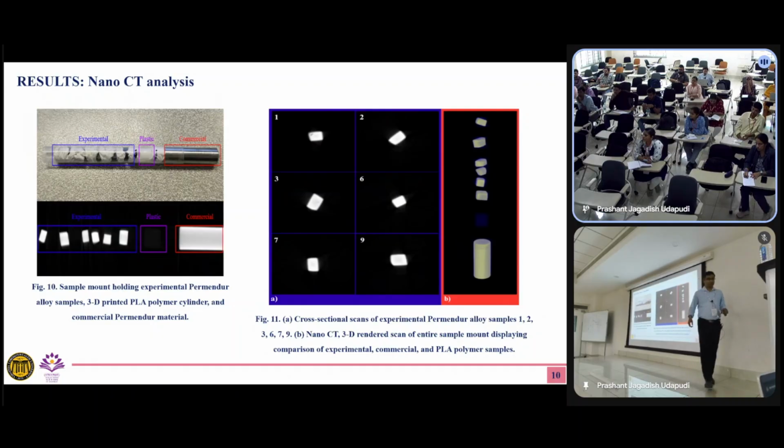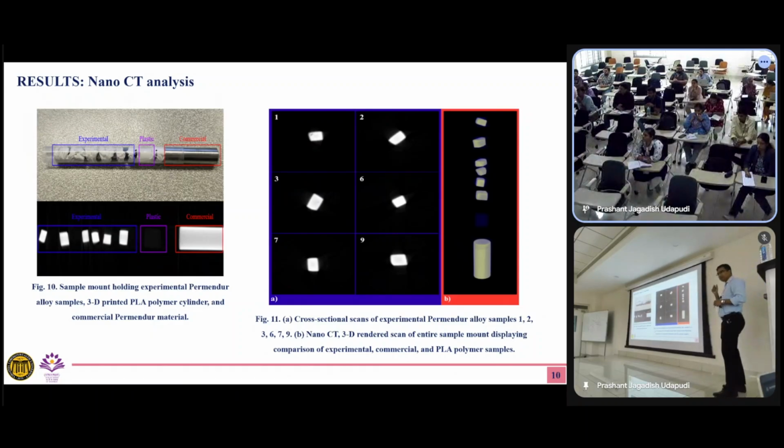Okay, so we still have to figure out how to. There will be some issues because when you print a large structure like that, there will be issues with crack formation. It may not form the entire nice shape. It's also quite tall, right? So if it was not tall, it would have been okay. But if it's quite tall, the bigger the material, the higher the chances of having defects. It's as simple as that.